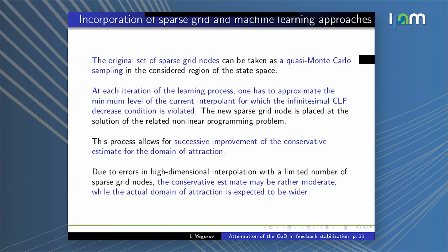And this is done offline. Then if after a certain number of iterations our sublevel set becomes large enough, then we can say that if we are online and we start inside this sublevel set, and if the disturbances aren't very large, and if we don't leave this sublevel set, then our approximate controller, which is based on interpolation and is much faster than the controller where we recompute everything, will actually steer our system asymptotically to the origin.